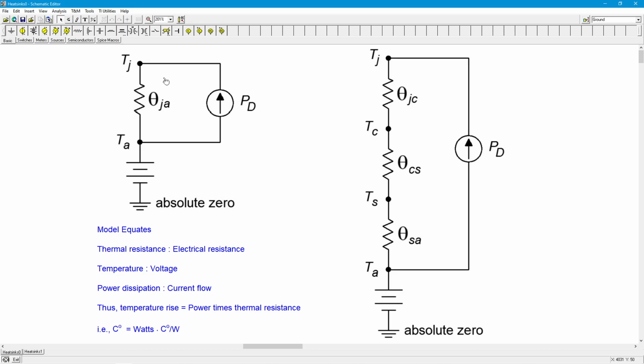Now, if you have a heat sink, like you would with that 3055, then you have the theta JC of the transistor, the interface, theta CS, and the theta SA of the heat sink. And here's the trick. As I said before, you could think of this as split into two parts, a theta JC and then a theta CA, case to ambient. Well, this stuff here, the heat sink, produces a lower number than that case by itself. Let that sink in for a sec.